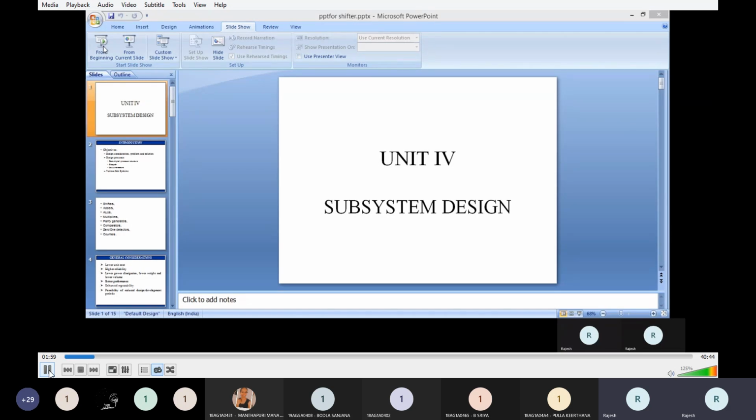We also covered a topic called NMOS fabrication, where, using these fabrication steps on the various layers of silicon, we have implemented an NMOS, two N plus regions in a P-type semiconductor, and PMOS, P plus regions in an N-type semiconductor, and CMOS, complementary MOS, consisting of NMOS and PMOS.